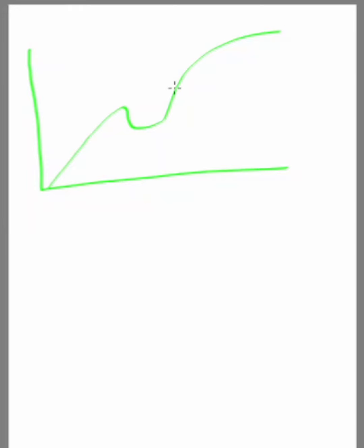Okay, you should remember the points. O is the proportionality limit and B is the elastic limit. This is the upper yield point, this is the lower yield point. First I will mark all the points. So this is E and this is F. G is the breaking point and F is the ultimate point.